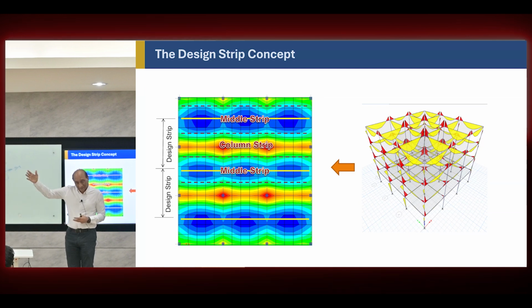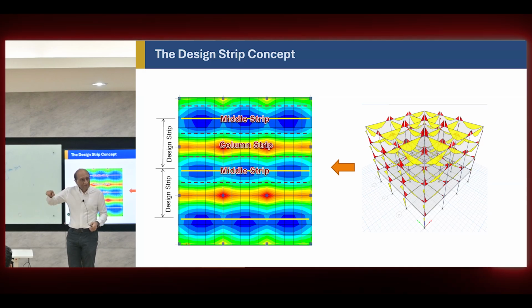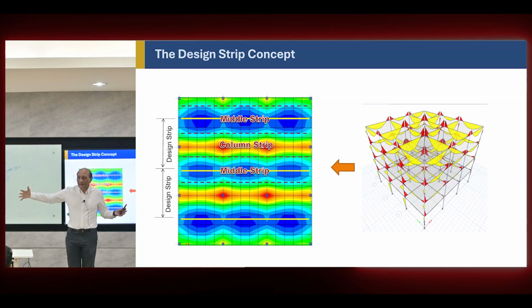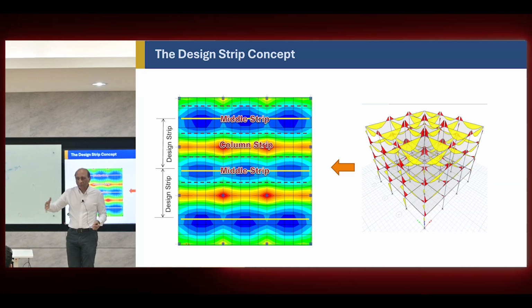So now the other direction load carrying doesn't affect it. So I can just analyze that strip as a one-way beam resting on columns with a very wide beam. It's just a very wide flat beam, and then I'm just putting it on the column and I can calculate the bending moment. This was a great idea.